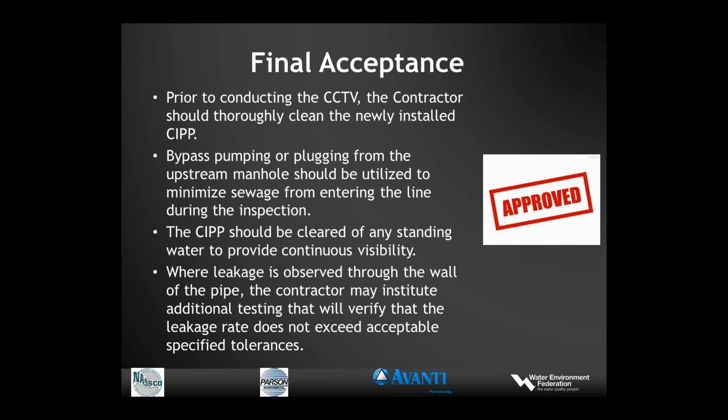Prior to conducting the final CCTV, the contractor should thoroughly clean the new cured-in-place pipe. There should be minimal sewage flow in the line during this inspection. If the pipe has a significant flow, bypass pumping or plugging is required. If there's standing water, like in bellies, that should be removed so you can get a good look at that